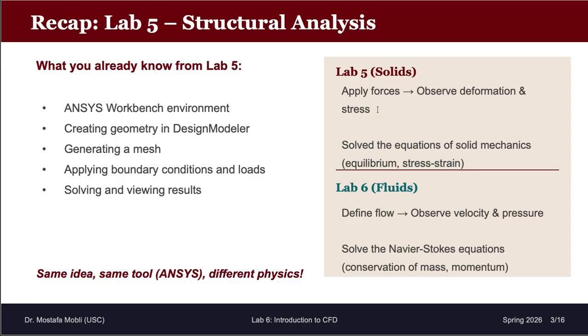We did apply forces and then observe deformation and stress, which essentially means that in the back end we did solve the equations of solid mechanics, the equilibrium equation and stress-strain equations. For lab 6, which is focused on fluids, we are going to define flow. We are going to observe velocity and pressure distributions, pressure heat maps and contours. We are going to solve the Navier-Stokes equations, which essentially means that we are going to solve the conservation of mass and momentum equations. This is done by the solver, not by you.